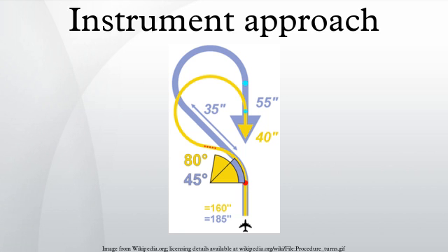Decision height or altitude. A decision height or decision altitude is a specified lowest height or altitude in the approach descent at which, if the required visual reference to continue the approach is not visible to the pilot, the pilot must initiate a missed approach. The specific values for DH and/or DA at a given airport are established with the intention to allow a pilot sufficient time to safely reconfigure an aircraft to climb and execute the missed approach procedures while avoiding terrain and obstacles.